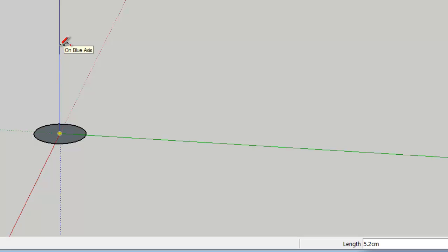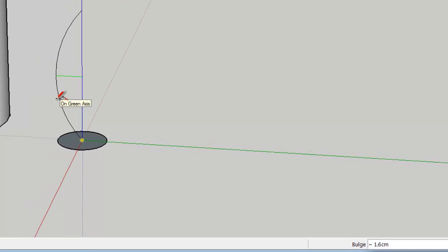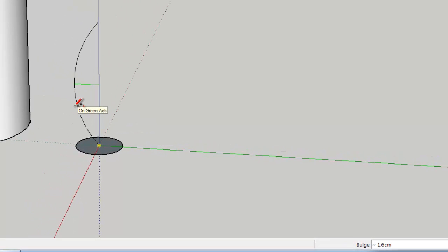Don't click. We want to enter the height. So take your hand off the mouse, and enter the following arc length. It's the length of this arc, and the length is 8. So just 8, enter. Now nothing is apparent except the word in the bottom is changed to bulge. But take your mouse and now don't click on it, just pull out and you'll see there is my actual arc. So I couldn't see it even though I'd entered the 8, but when I move the mouse the arc will now appear.